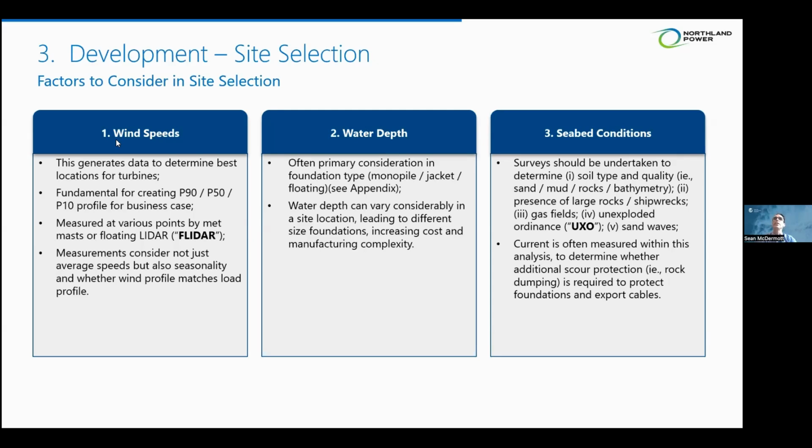Seabed conditions. What are you drilling in? What's there that you might disrupt or that will make the construction more or less difficult? In Northern Europe, a lot of the early projects were located in areas that had been mined through World War I and World War II. So unexploded ordnance was a huge consideration. In Nova Scotia, as we think about moving out to areas in and around where we've had historic gas fields, that's something that is an important consideration.